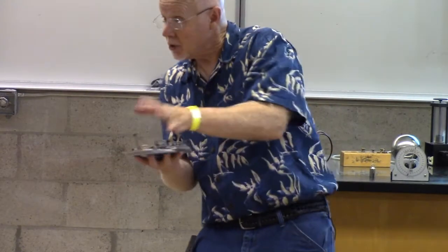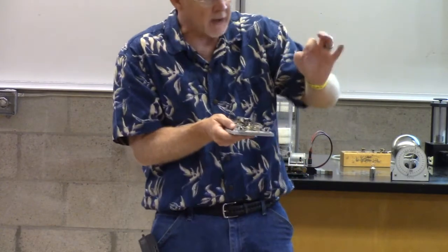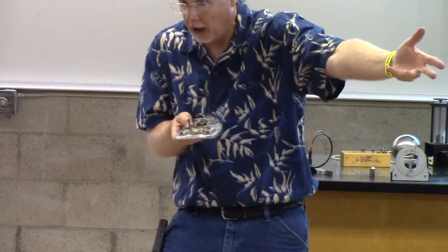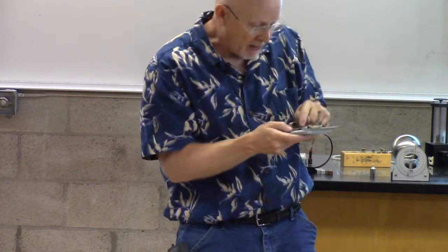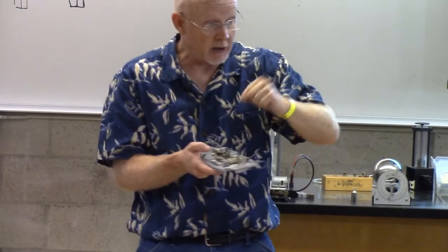Once the iron gets to a certain temperature, the bimetal strip would expand, breaking the contact, and the electricity would turn off. Now, it's still plugged in, and on top it still says on, but it's not making contact, so it's not heating up my iron anymore.